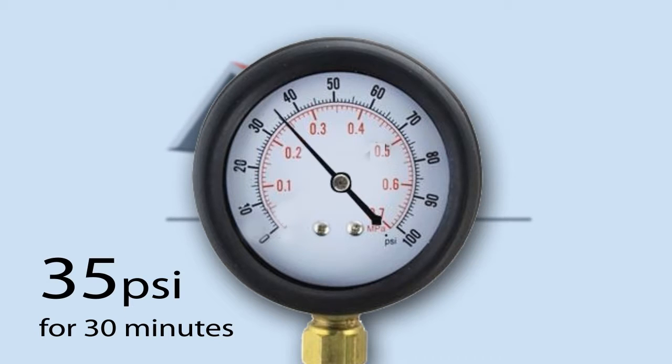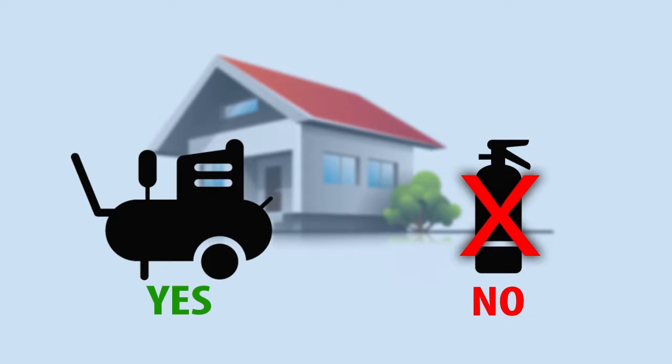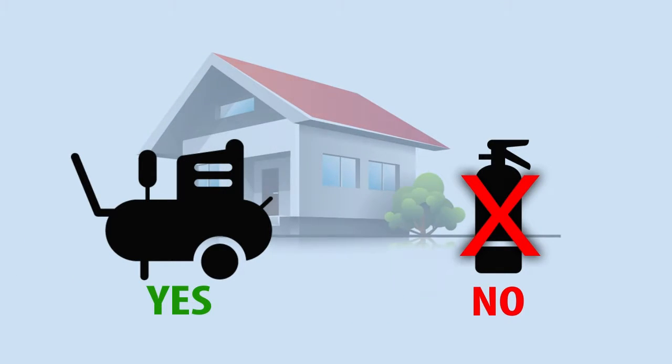The results of the pressure test, pass or fail, need to be documented on the update. Keep in mind, the use of air tanks is not permitted to blow the water lines.